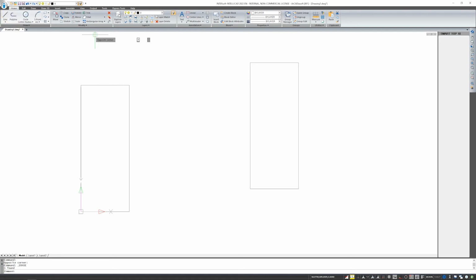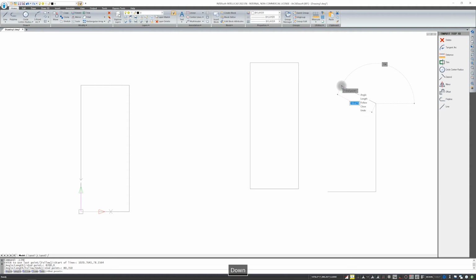When I start drawing and entering data and I realize that I have introduced some data incorrectly, for example, now I have introduced the wrong value, we have different ways of using the undo option. 1, there's the Ctrl-Z option. 2, there's the undo from the arrow here at the cursor. And then there's 3, which is the undo option from the command area.